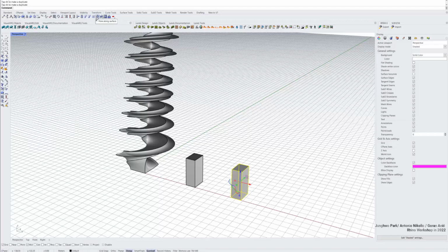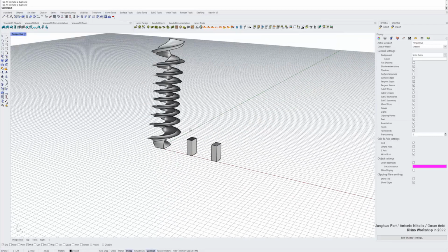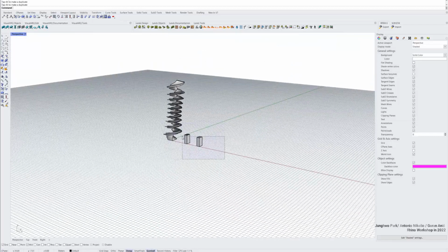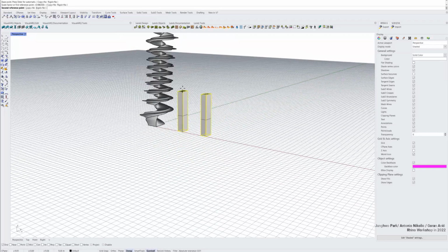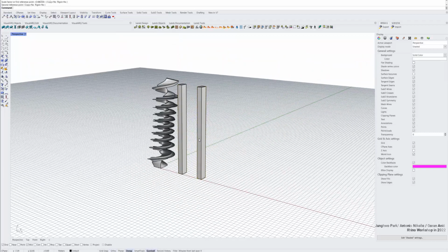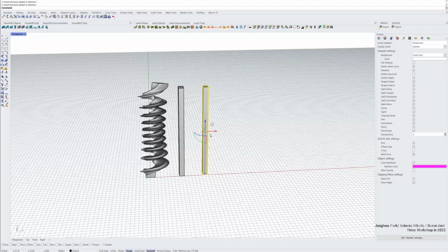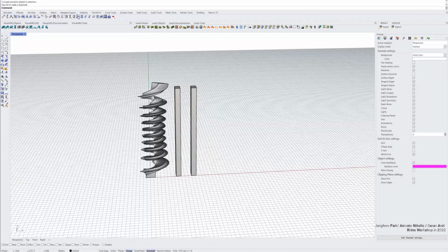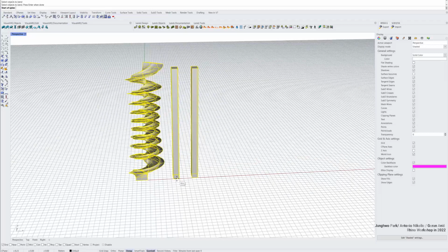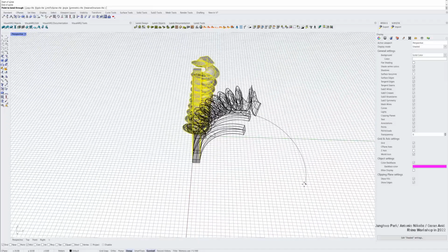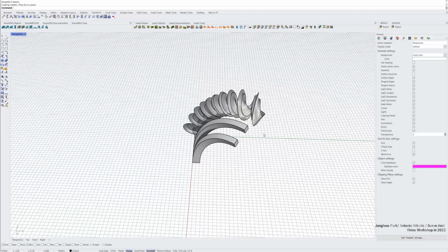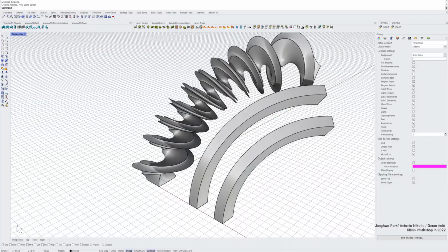But what could be interesting for you is that I scale 1D these objects and show you this bend. With all these transforms, we can choose more than one object. So if I want to bend, I select the objects and choose my midpoint there as a spine. As you can see, we can bend even more than one object, and you can really make complex geometry.